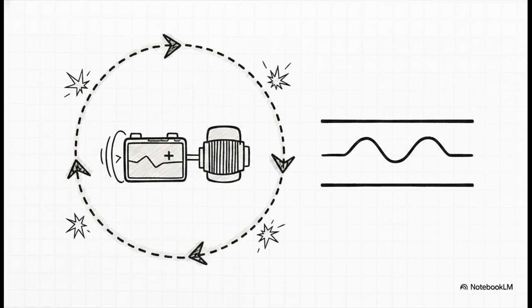Right, so the system gets tricked. It thinks the battery is fully charged, and it switches that heavy load right back on. This triggers an infinite, violently rapid loop of mechanical relay switching that will absolutely destroy your equipment. The solution? A clever engineer programs widely spaced hysteresis control loops. You set one extremely low trigger for the fallback and a completely separate, much higher voltage threshold before the system is actually allowed to recover.